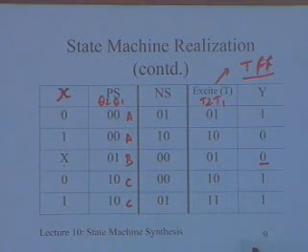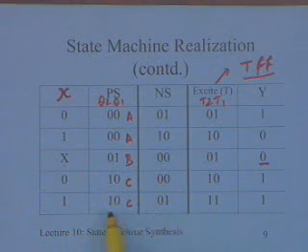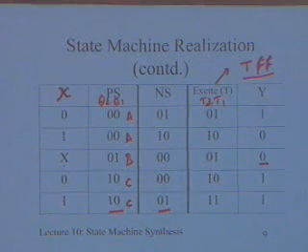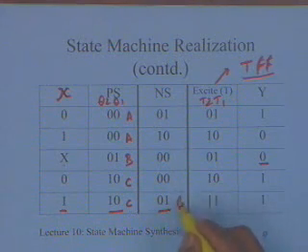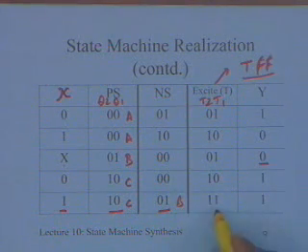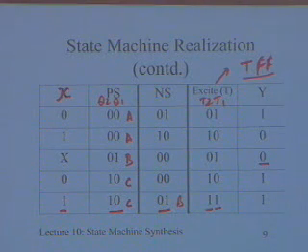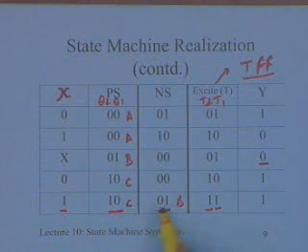Similarly, for example, to go from 1, 0 to 0, 1, for the input 1 when I am going from C to B, this corresponds to B, the edge going from C to B, I require to toggle both of them, so I require 1, 1. Because 1 is going to 0, and 0 is going to 1. Output was 1, that comes from the edge that was given.